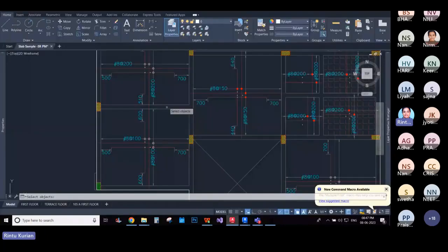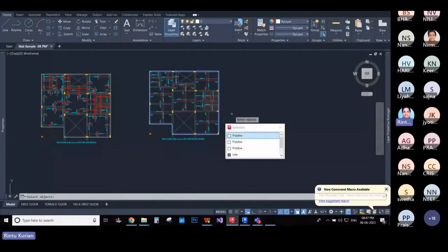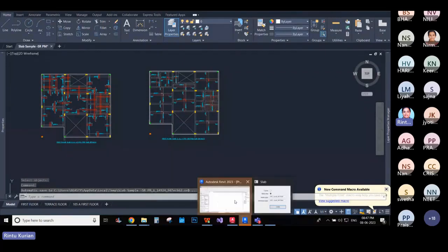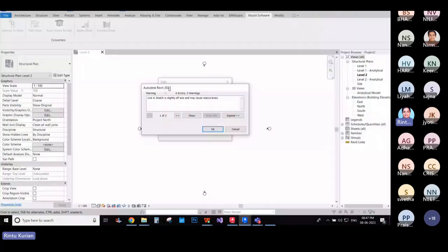Select the outline first. Then click enter. You'll have to click twice. Just wait. You'll see that Revit is blinking. Just come back. You'll see a warning. Don't worry about the warning. It's just because we are trying to use something using a plugin. Now the cursor is buffering again. That means we are ready to scan.